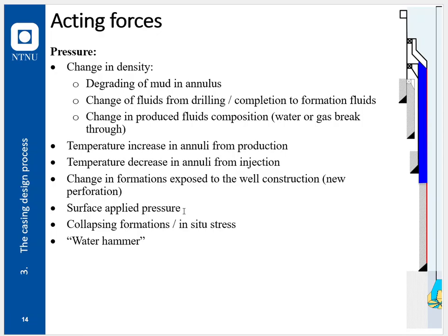Surface applied pressures, say you're doing a fracturing, say that you are initiating some new use of a well by perforating in an old well, shale formations, and fracturing them. That would be a typical example of just what was discussed. And the water hammer, the shocks that we talked about, perforating could be one of these shocks taking place in the well. Sometimes these are quite significant.